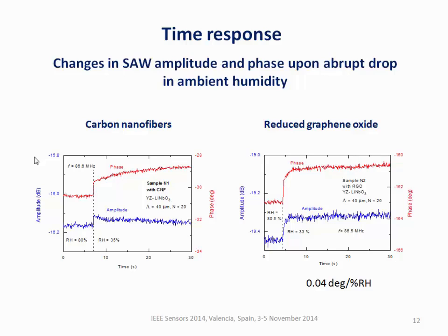We cannot change the humidity faster, so our limit for the time response measurements is about 0.1, 0.2 seconds. And so we observed indeed that the surface acoustic wave delay line with nanostructural films responds very fast to humidity changes.